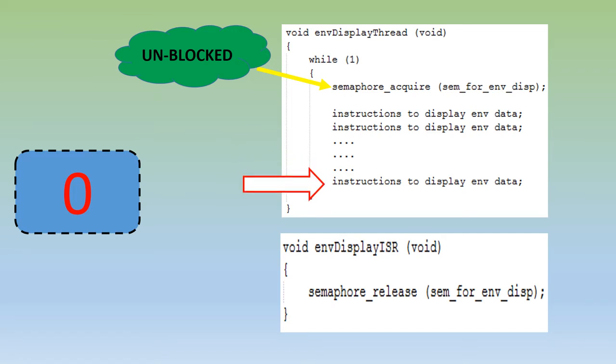So in summary, when a key is pressed, a hardware interrupt is triggered, which calls an ISR. The ISR signals the thread, and the thread does what is required. The ISR signals the thread with the help of a binary semaphore, so the non-mutex binary semaphore acts like a signaling mechanism.